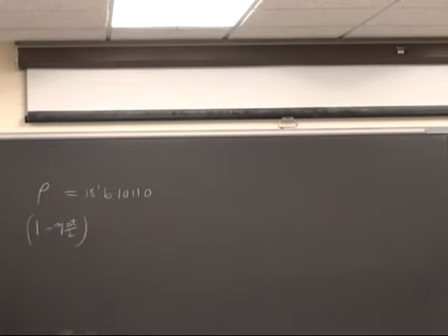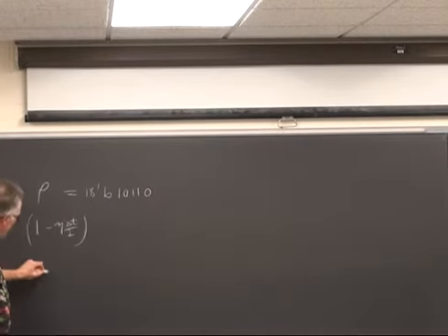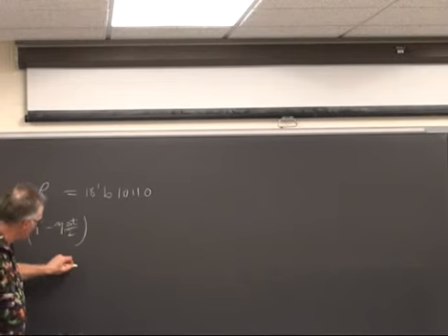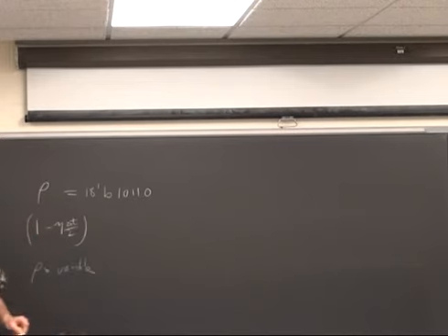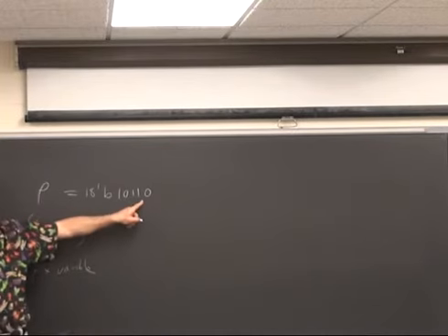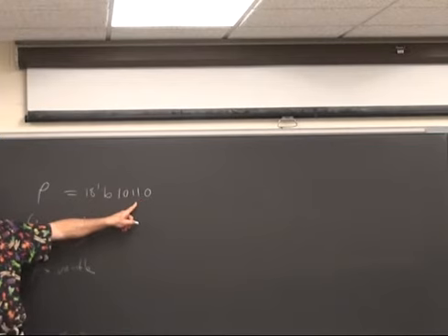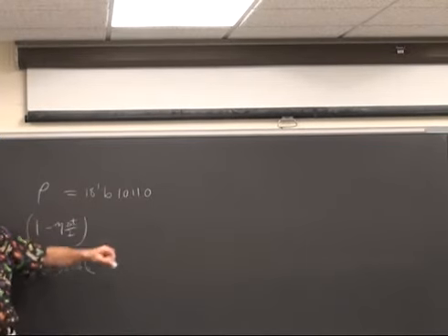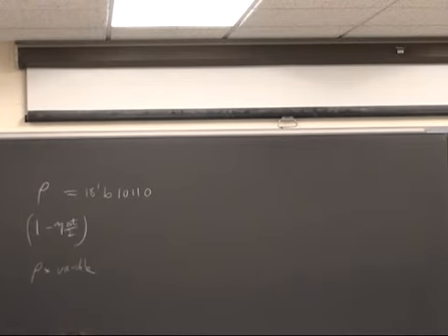If you assign this to be some bit pattern, what does Quartus do when you ask to do rho times some variable? Does it actually use a hardware multiplier? Or does it do the reasonable thing, look at the number of bits that are non-zero and implement this as shifts and adds? Anybody tried that?